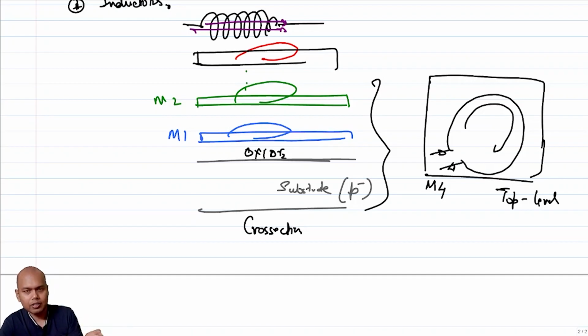And number two, the more important problem, is that these metal layers all do not have the same resistivity. The other thing you'll have to take care of is, the moment you get hold of a technology in which you are planning to design an RF system, you have to characterize the resistivities of each of these metal layers. Generally, in a process design kit, if it is an RF friendly process, the top level metal will have the least resistivity, and the lower level metals generally have higher resistivity. Again, this is not sacrosanct, but if you get hold of an RF process, this is what one might generally see, right?